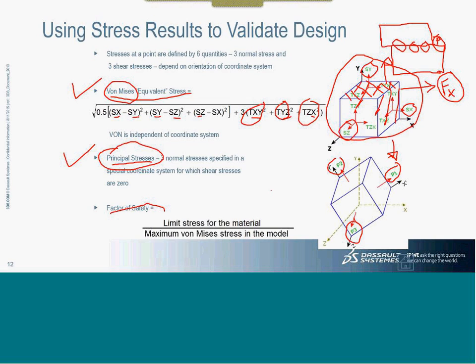So typically, instead of thinking of stress values, people discuss factor of safety, which quickly tells them how safe their part is. If I talk in terms of megapascals, it does not make sense most of the time. Instead, if I say the factor of safety is 1, 2, or 3, that tells how safe this design is. That makes it simpler.